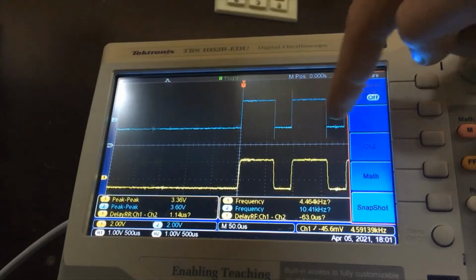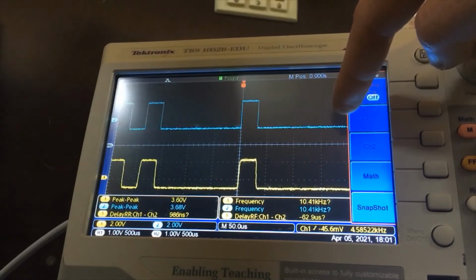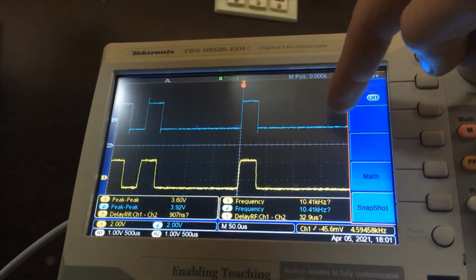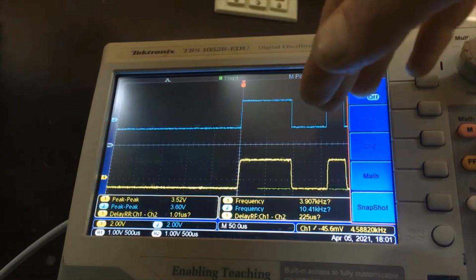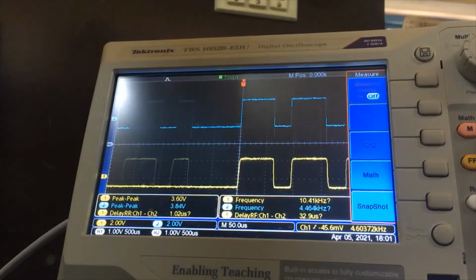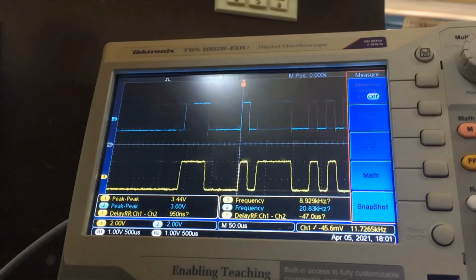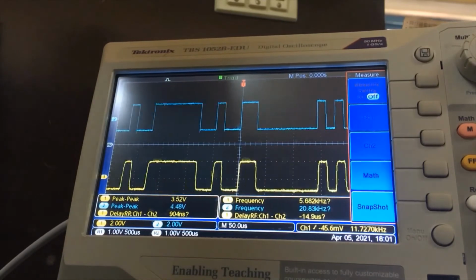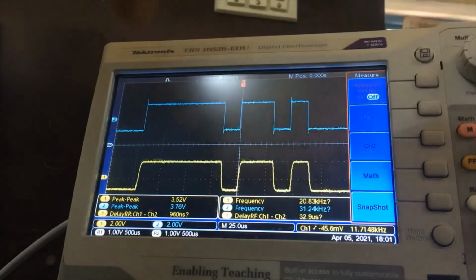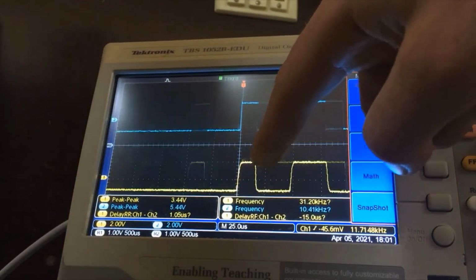One thing to mention is that these values are continuously changing, because if you remember, the message which we transmitted was a sinusoidal waveform, and the sinusoid changes continuously. So these values, the ones and zeros, are actually changing, encoding these values. Now I increase the sampling frequency. You can see the edges have started shifting. This is because now these higher frequencies are not allowed to pass by the channel.